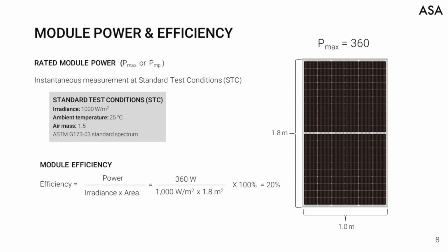When estimating a building's energy potential, it is helpful to put module power in terms of per unit area, or power density. In its most basic form, this is done by dividing module power by its area. That said, one may want to relate efficiency to power density. To get from efficiency to power density is easiest with metric units. You simply add a zero.